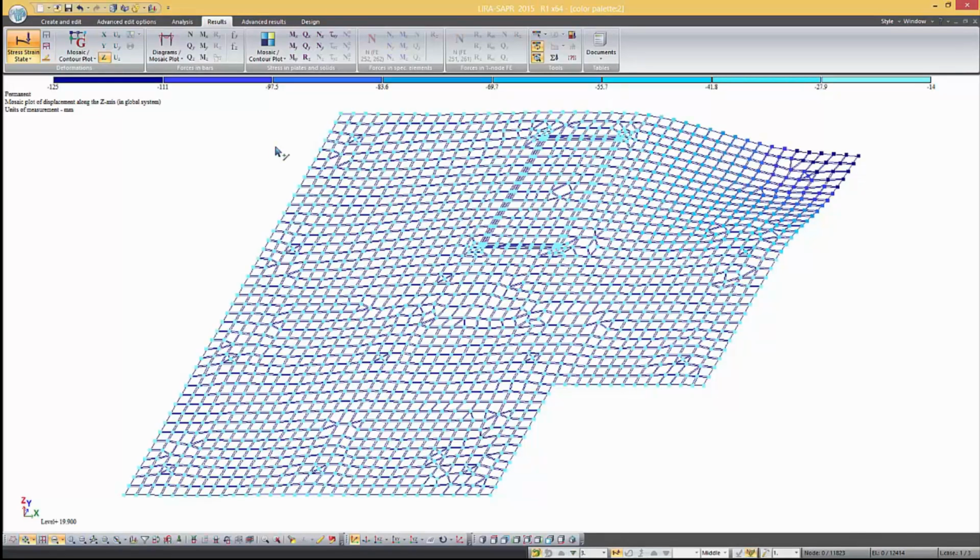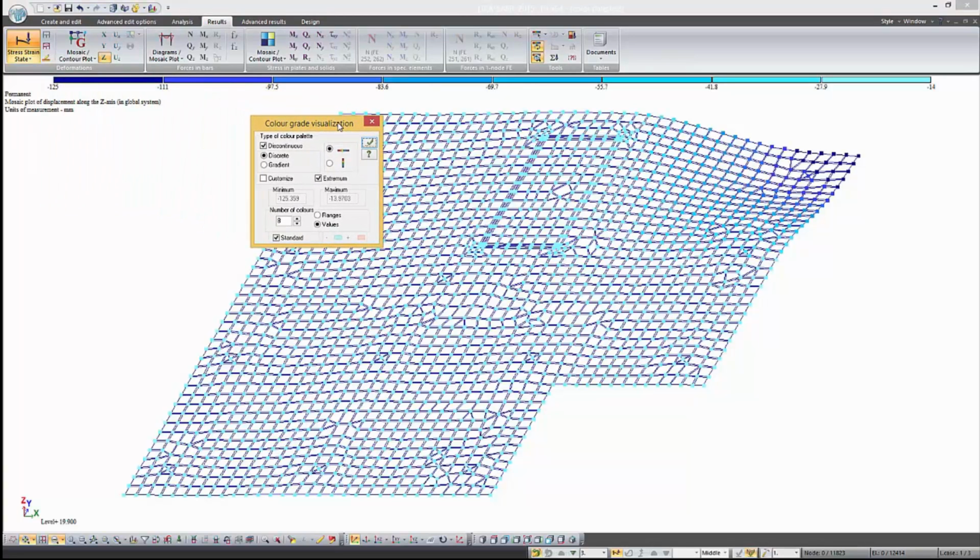On the Tools panel, open the dialog box Parameters of Color Palette. The opened dialog box displays the parameters that can be changed for more comfortable user work. There are two kinds of Color Palette display, Discrete and Gradient. Discrete Color Palette represents discontinuous color segments that in turn are divided by numeric values. Discrete color palette is initially displayed by default.